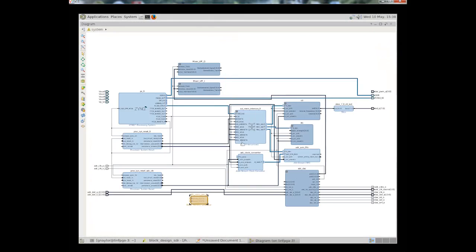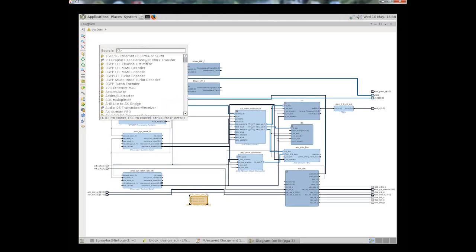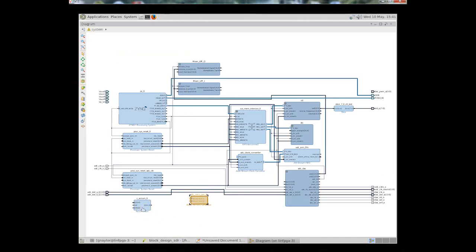Okay, so we carry on now. Here's our block ROM, and we need to drive this with a triangular wave, a ramp waveform, which is going to step through all the locations of this sine wave. So to do that, we're going to use an accumulator. So we will parameterize this now.